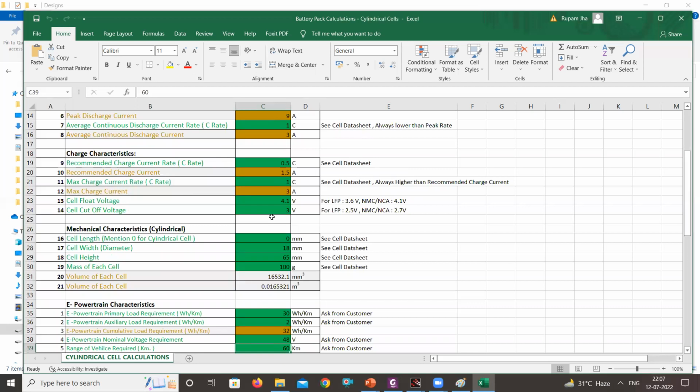Okay. So the more energy you will require. This efficiency is in general considered for a plain road, and that's why the drive cycle concept is there. The drive cycle concept takes into consideration a maximum 5 degree inclination. Like, in a plain region you are traveling, but there is a flyover, so there will be an inclination. That inclination is continuously at a 5 degree angle, so that is up to what the drive cycle covers. But if you are traveling in a continuously hilly region, the efficiency would drop. You need more power, and for that a separate powertrain would be required. It is not the common powertrain for each region. And that is the reason the EV has not been successful yet in hilly terrains. Okay.